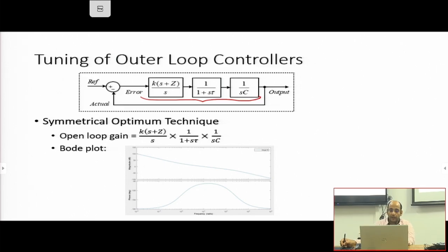Okay. Now this is your minus 180. Whatever is available with you here, this is my phase reserve. Correct? This reserve will become my phase margin if the frequency where it has this peak becomes my gain crossover frequency. So for example, in this plot that I have shown you, gain crossover is somewhere here, let's say.